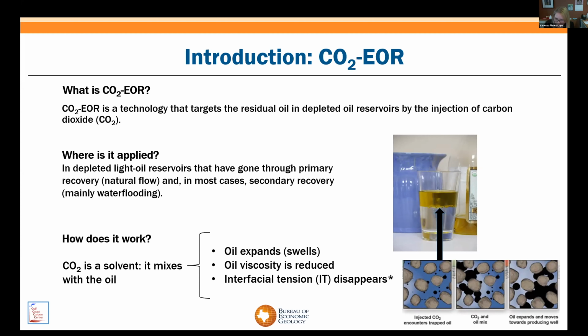But when that happens, the physical forces that hold the two phases apart, the CO2 and the oil, which is called the interfacial tension, will effectively disappear. And so they combine, forming a new phase. And this new phase will also expand, and its viscosity is going to be reduced, which improves mobility. So this enables the CO2 to displace the oil from the rock pores, pushing it towards a producing well or an extraction well.